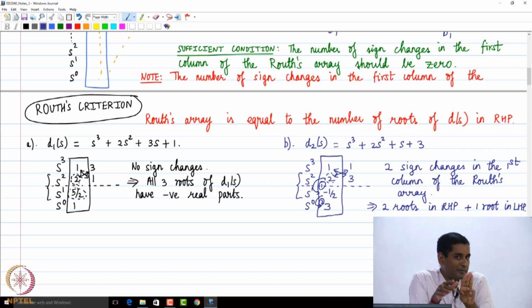So this is a third order polynomial, right? So totally there are going to be three roots. Two roots are in the right half of the complex plane, so we are left with only one root. Where does the one remaining root lie? Obviously, there are two ways to eliminate the j omega axis. First is by looking at the Routh array, you see that there are no zero entries. As I told you, tomorrow we will look at special cases. That rules out the j omega axis.